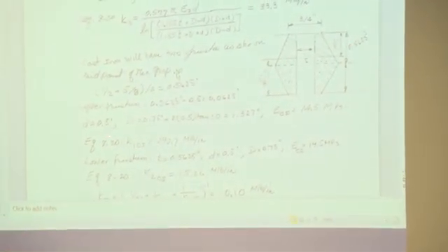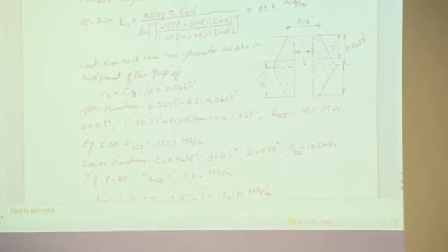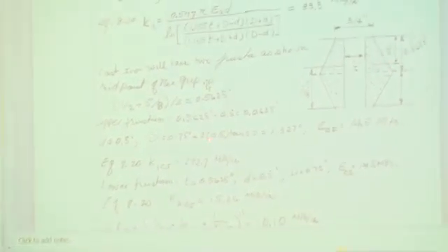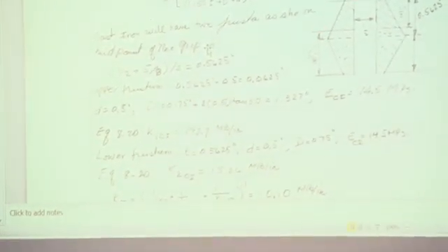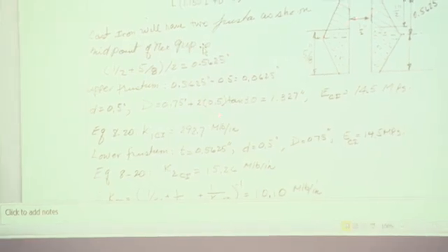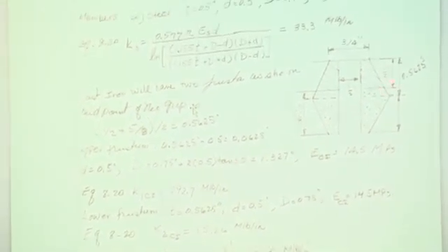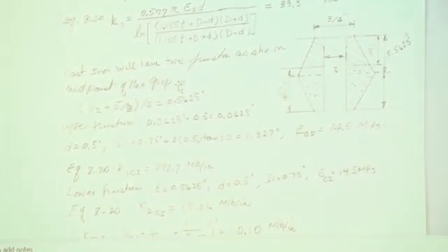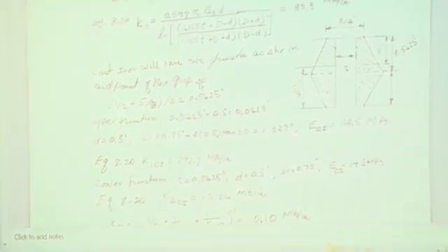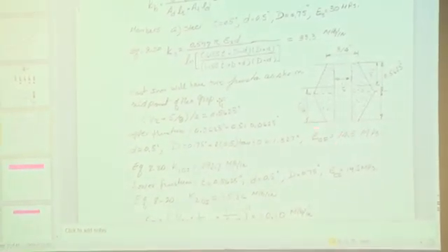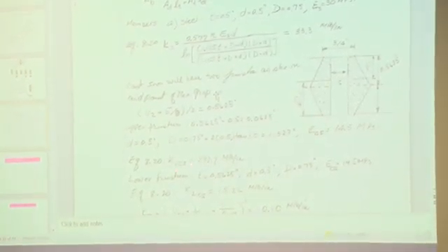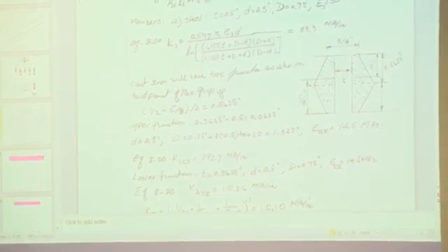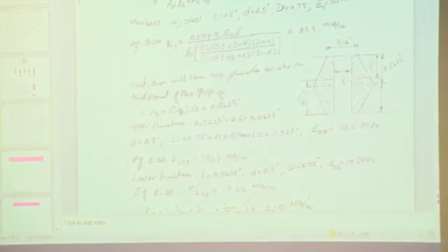Now, for the middle one, we have d still equal to 0.5, but capital D is that distance, which is 0.75, that, capital D, plus 2 times 0.5 tan 30. Those 2 little pieces that I was talking about when we did this, that come from the distribution of the load. You put them all in that top equation again, and you find another value for an E of cast iron, of course. You find another value for the stiffness of the cast iron member in the middle.